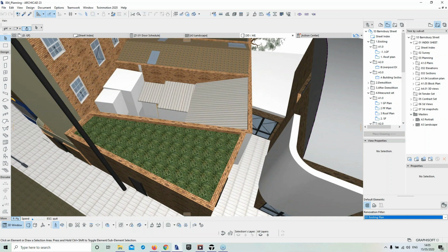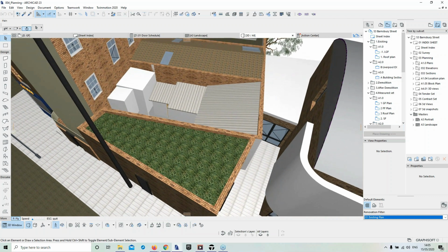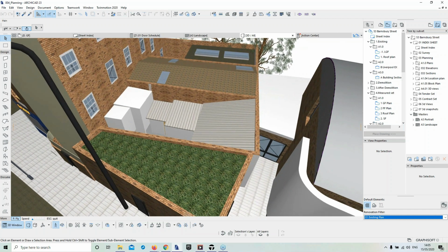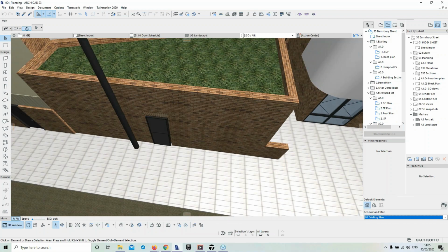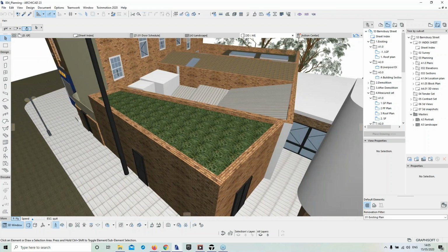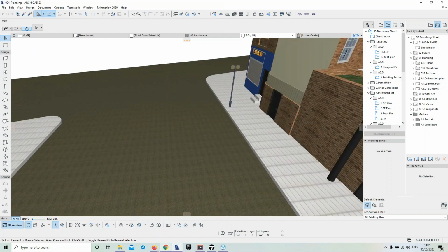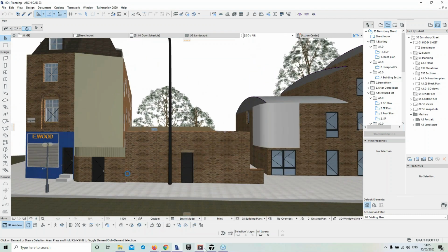The first thing we do, go on site, take measurements, or have a company take the measurements, of course, and we create a 3D model within ARCHICAD that we feel is accurate, and we can base our design decisions on it. Once we have the model, we always cross-reference it with the actual site from Google Maps, for example, which now gives you a lot of information with regards to the 3D dimensions of the site as well, not only images.